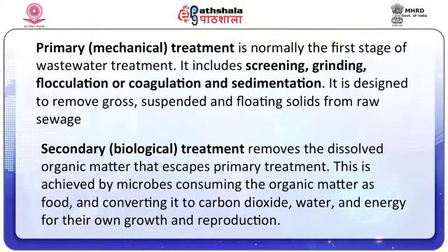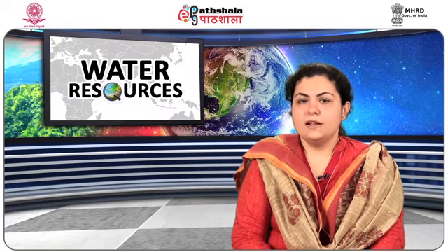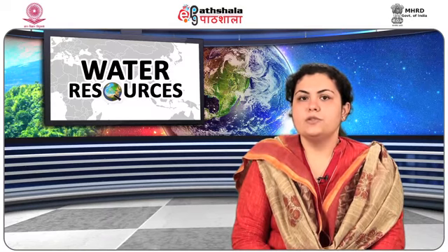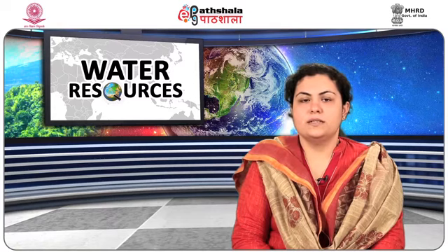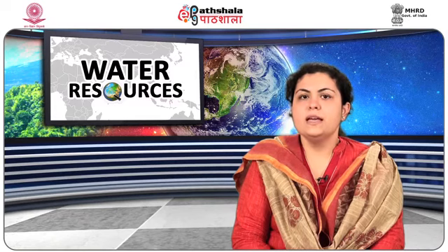Secondary or biological treatment removes the dissolved organic matter that escapes primary treatment. This is done by bacteria consuming the raw matter as food and converting it to carbon dioxide, water, and energy for their own growth and reproduction. The biological process is then followed by an additional settling tank to remove more of the suspended particles. About 85% of the suspended solids and BOD can be removed by a well-running plant with secondary treatment.